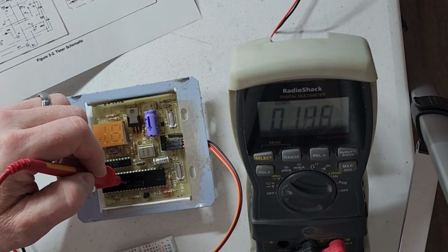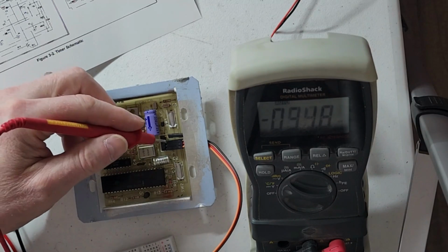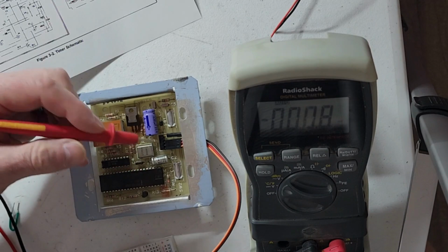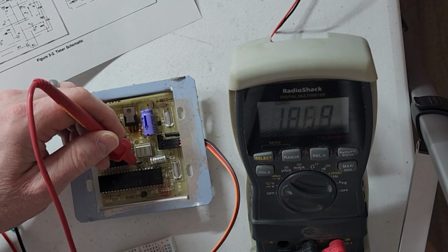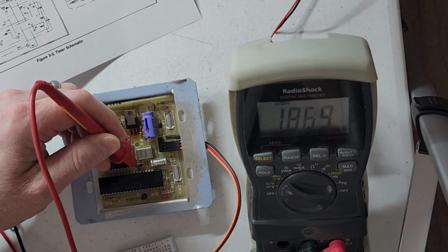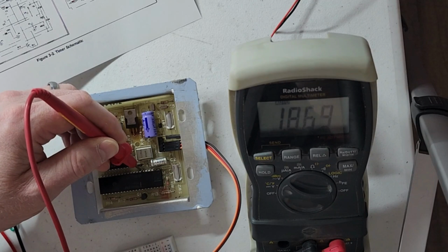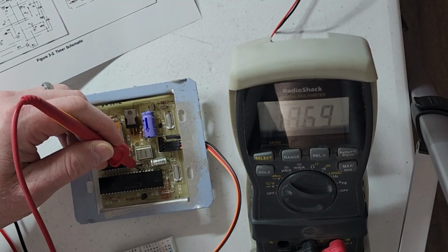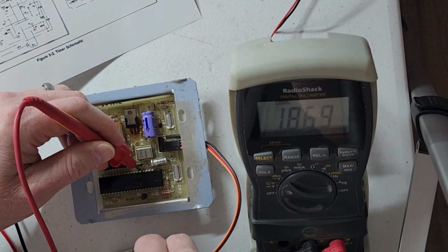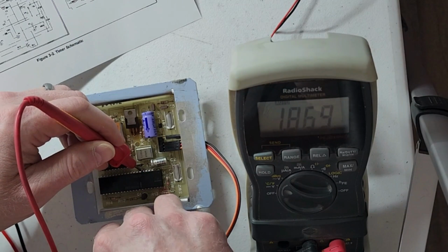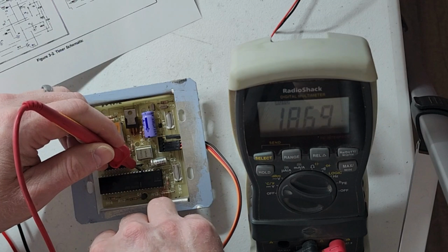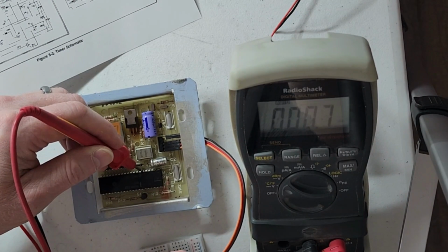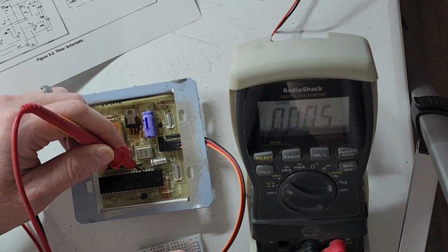I thought I knew where it went. Oh yeah, I think it goes to pin 6. Let's see. 1, 2, 3, 4, 5, 6. I looked this one up, I think. Yeah, there's that 1.86 volts, coming from the float. Actually, right now the float is not connected. It's just open. And if I short it to ground, we're going to see. See, I short it to ground. Yeah, so it is that pin 6.